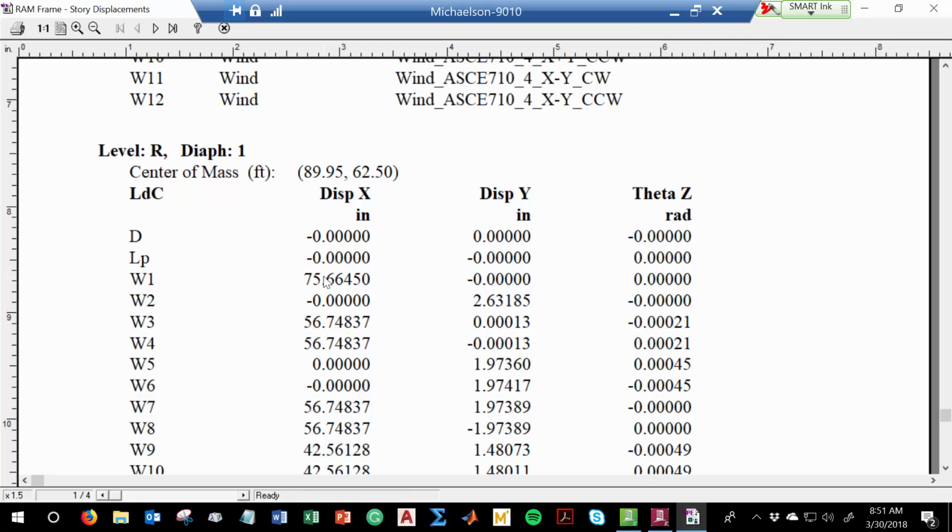But listen to me. This is where the iterative nature comes into play. They're like W10 by 33s. So take those W10 by 33s and turn them into W10 by 95s or whatever. And now monitor it. Once those values get within acceptable limits, then you know you got your size. Now, if you look at the y-axis, it's only displacing like 2 inches, like 1 inch, and so forth. Does that make sense? Now, I'm sure you're asking, what's the tolerable drift limit? It's in some of those design guides that I'm going to make you all do some research on.